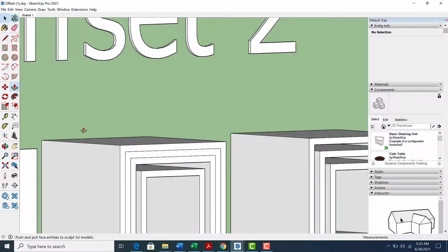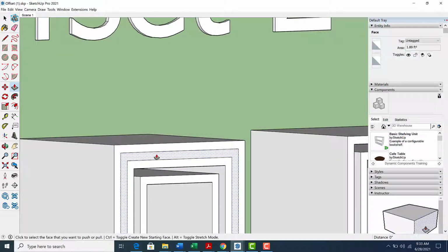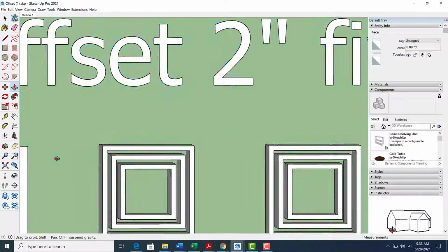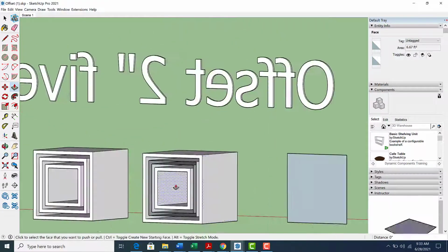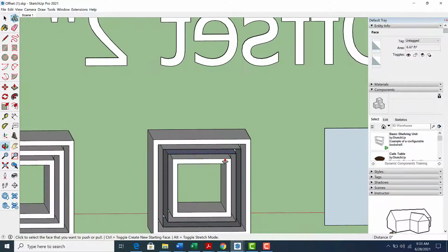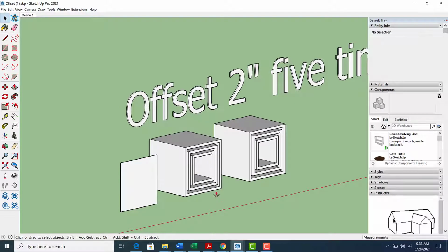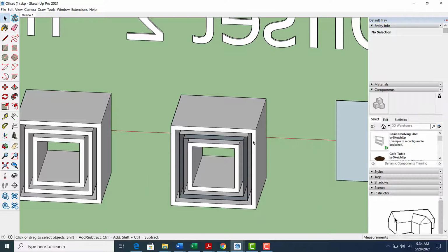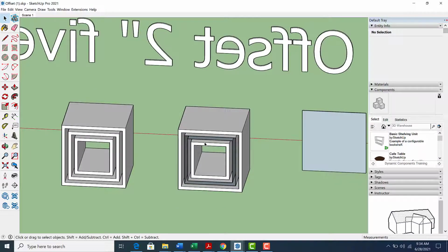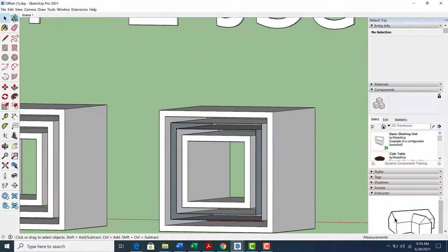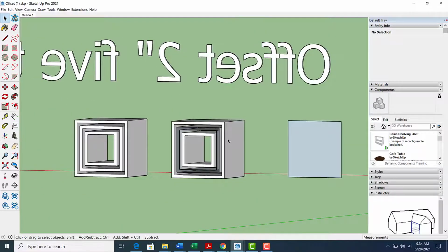So I just go to the push-pull tool, show this surface, and if I double click, it would match the depth, remember? And again, as you can see, there is a hole here. The other way that I can copy this with less effort, there is no need to go and draw a line and delete to cover this part and then delete the other part.